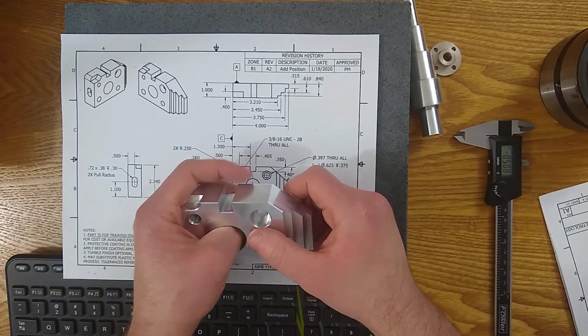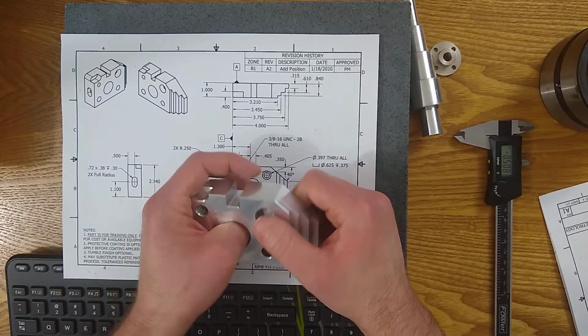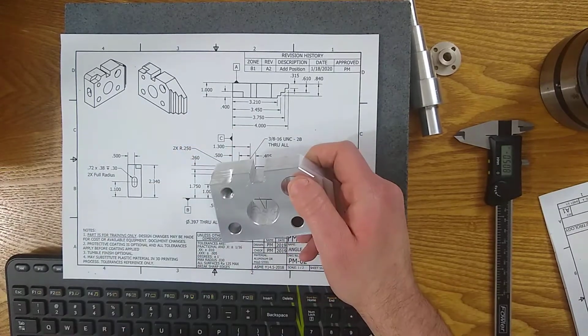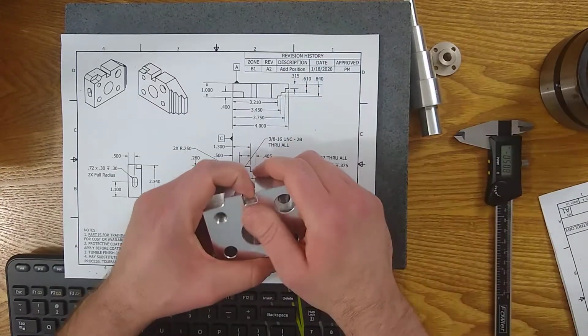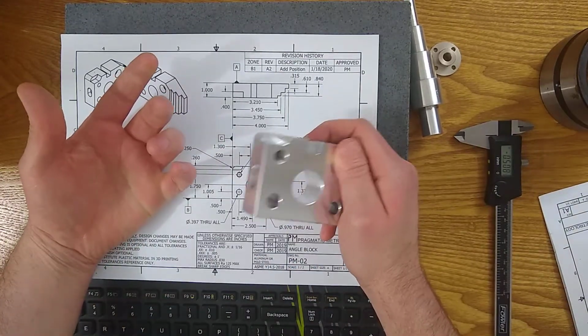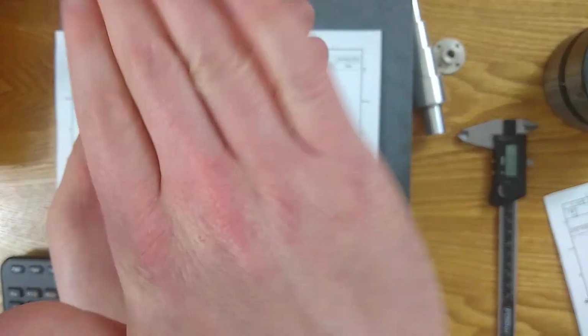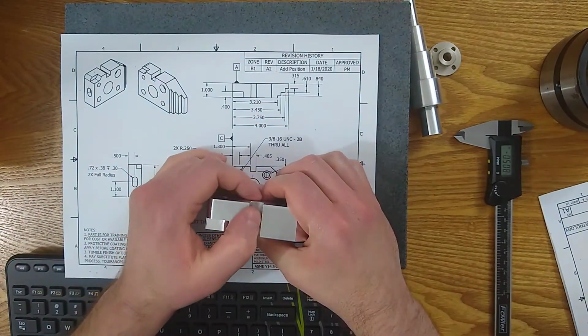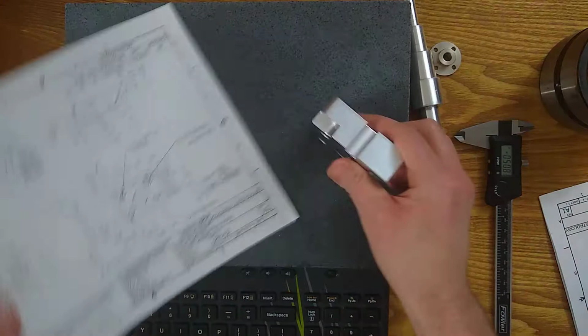And then the last one for tapped holes, or second to last one, depths are minimums. So if you had a depth of 0.75 on that tapped hole, that's a minimum. Now that 0.75 gets the same title block tolerance, plus or minus. I probably should have called that as a fractional or as a 0.8 to get the most tolerance.